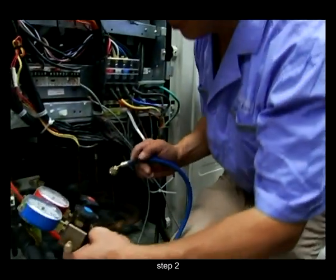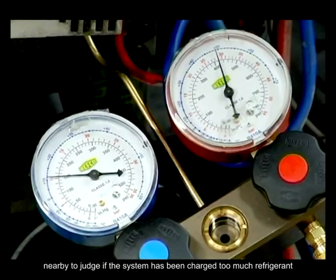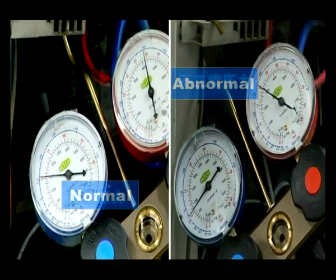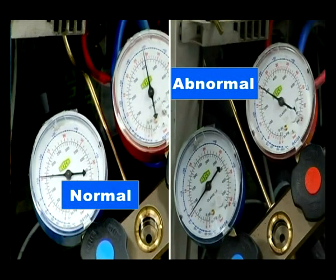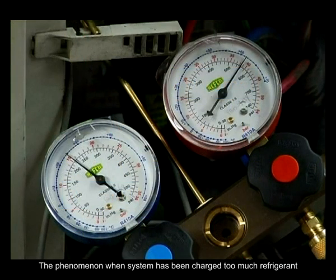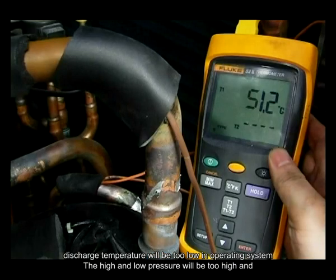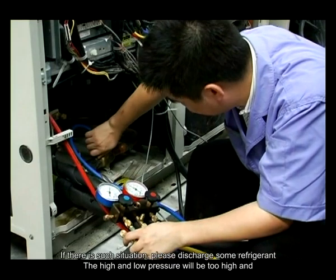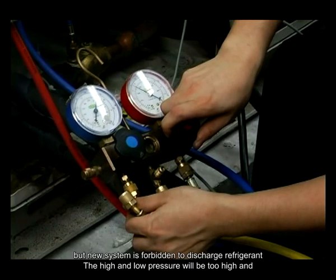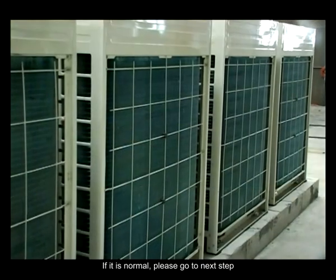Step 2. Measure the system pressure and compare with the normal system nearby to judge if the system has been charged too much refrigerant. The phenomenon when system has been charged too much refrigerant. The high and low pressure will be too high and discharge temperature will be too low in operating system. If there is such situation, please discharge some refrigerant, but new system is forbidden to discharge refrigerant. If it is normal, please go to next step.